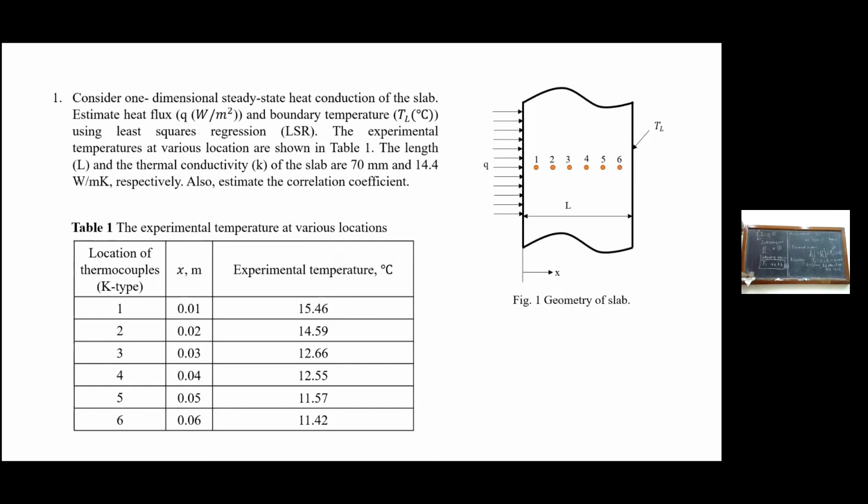So this is as far as the forward model is concerned. In a typical quiz 1, this is a very simple question. In a typical heat transfer quiz, we will say if the left side is at 30 degrees centigrade and the right side is at 10 degrees centigrade, what you will do is x equal to 0, T equal to T1. X equal to L, T equal to T2. These are called boundary conditions.